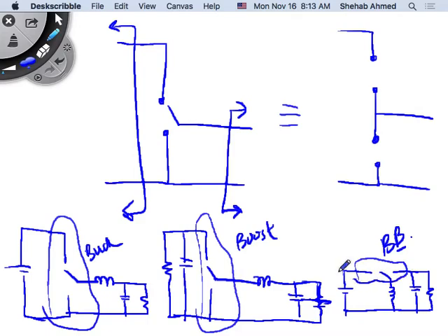Maybe in the buck boost they drew it differently, but you can draw it standing up and figure out a way to make it look similar. At the end of the day, these two terminals always have a stiff voltage source across them. And the output terminal of this circuit that's connected to this moving pole or moving arm always has an inductor that maintains current continuous for that switching period. Here, same thing.